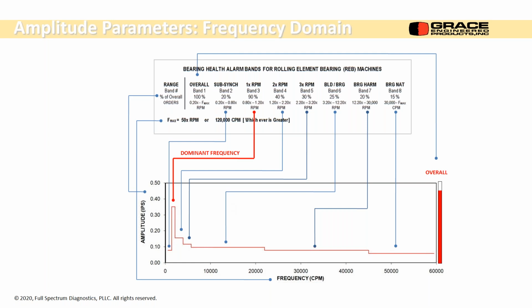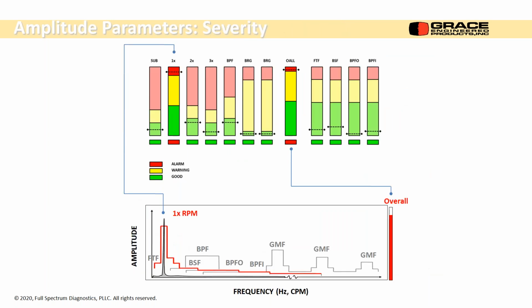So the database setup is always changing, and it's got some really good capability. You just have to have some ideas on how to do the statistics. This would be what this is like. So I have a bin for my 1 times RPM, and basically I can do a spectrum, put a filter on 1 times RPM, and pull that value off. I can also do it for blade passing, for bearing frequencies, for gear meshing, all the different things in here.